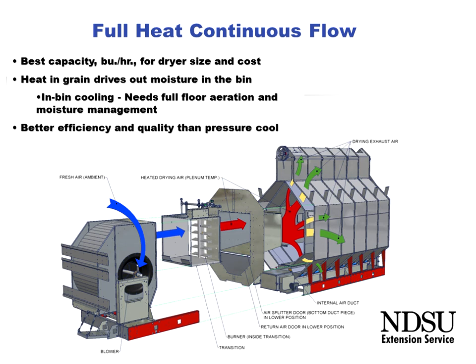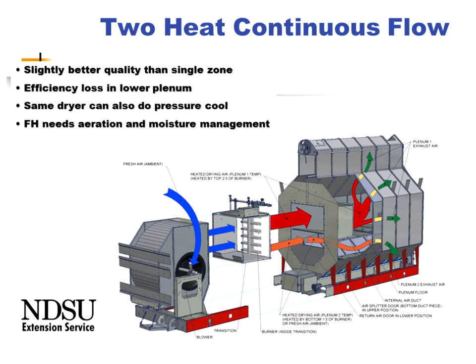So rather than taking those last 2 points out in the high temperature dryer, we're dumping this dryer at maybe 17% moisture and moving that corn into the bin, cooling it a little bit slower in the bin, and in that cooling process we're picking up a couple points of moisture removal. So we increase in speed, we increase in corn quality, and we increase in drying efficiency.